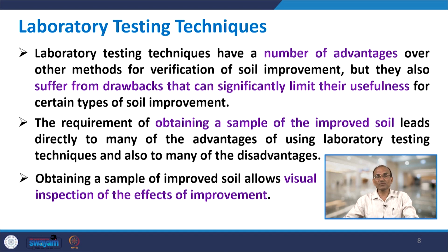Obtaining a sample of improved soil allows visual inspection of the effects of improvement. So, first of all, this is a good point: if you collect a sample of the improved soil, you collect a sample from the site which is not improved and another which is improved, and then test them in the laboratory.